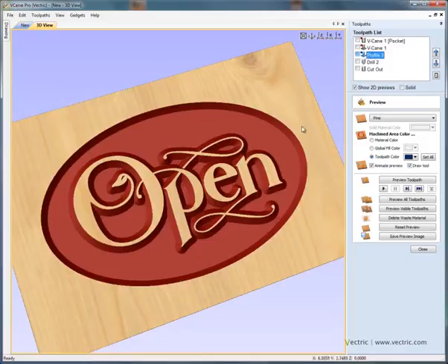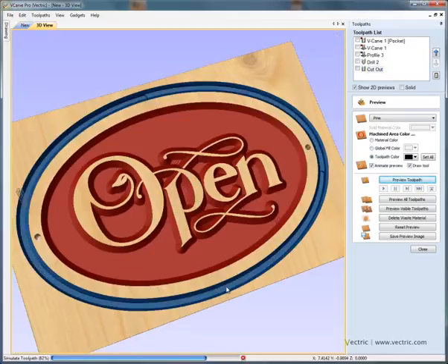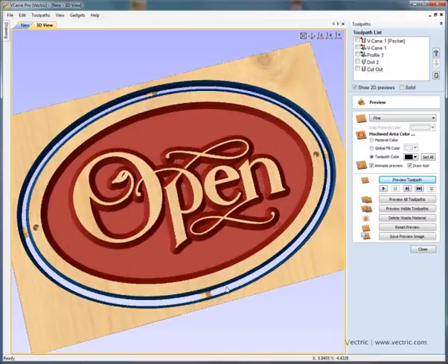We then profile machine a chamfer around the sign. Drill some holes. And finally cut the piece out. But instead of cutting all the way through, we've added little bridges that are going to hold the project in place and stop it breaking free.